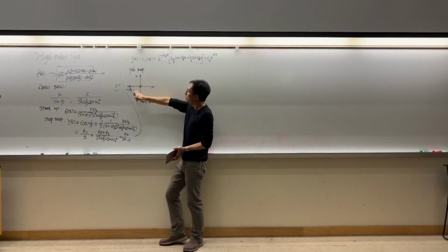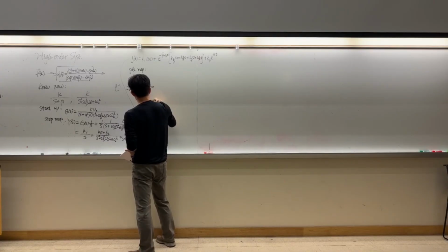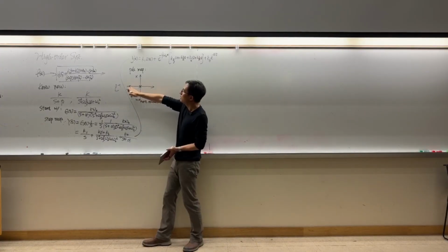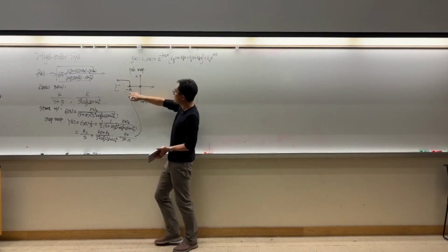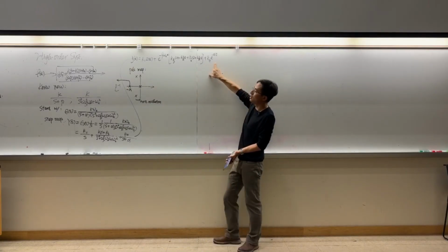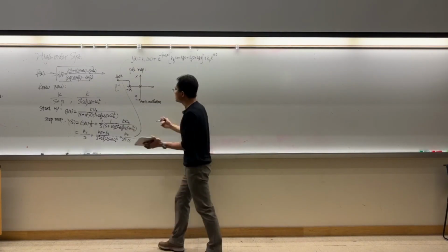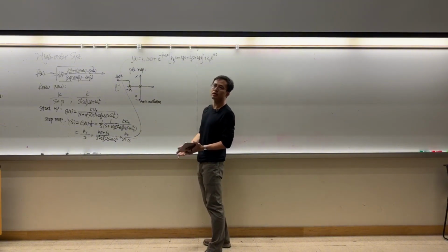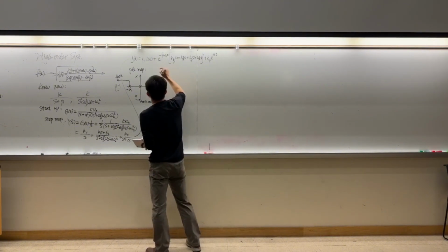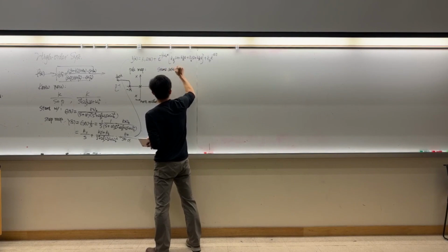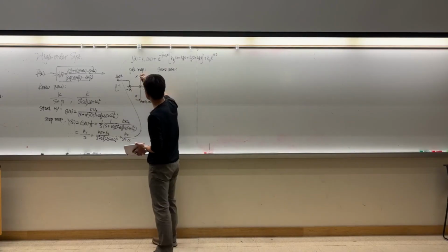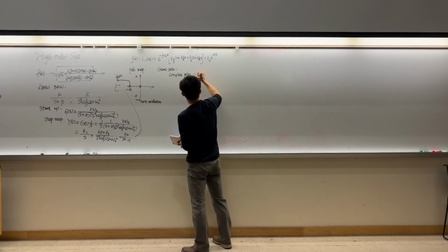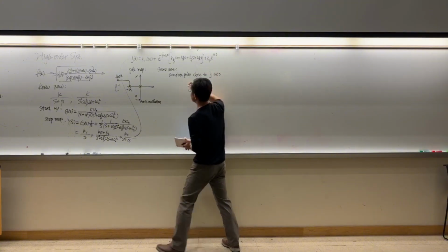And then if this pole moves more towards the left, would this component be decaying faster or slower? Faster, right? So let's now just consider some boundary extreme cases. So in the extreme case, let's say the complex poles are close to the j axis, the imaginary axis.